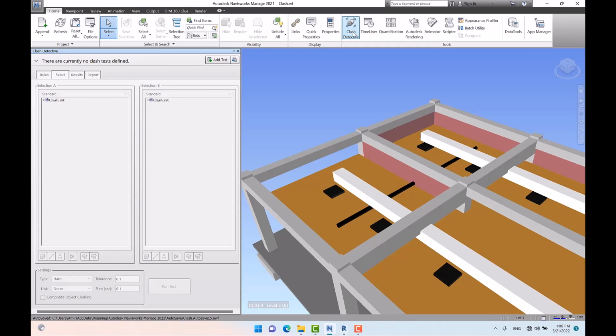And we have the same thing with the floor, that the places of the pipes are going to be voided in the floor, so it is not considered as a clash. And we do not consider walls and floors in the clash detection, so these are not necessary in the clash detection process. As a result, some objects are not engaged in the clash detection process at all. So we cannot specify the whole project in the standards for checking the clashes, because we should classify the standards as I told you. For example, beams and ducts, beams and pipes, or ducts and pipes. And I will share an Excel file with you in which the standards are mentioned, so that you will be informed about the standards of the clash detection.